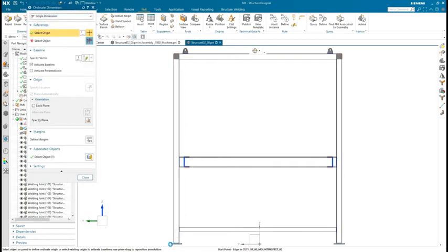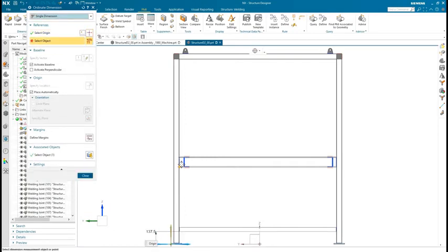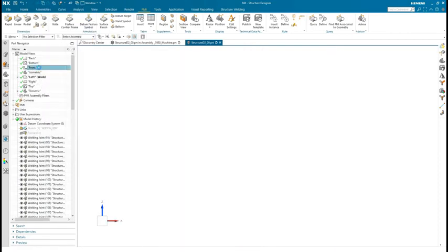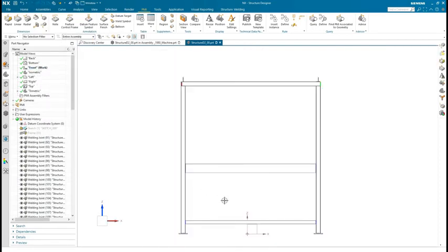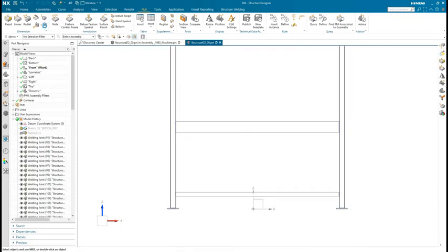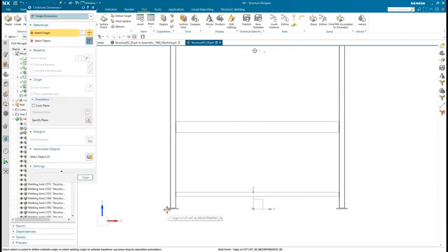We'll start with ordinate dimensions on the left view. We'll only need to add overall and location dimensions since the parts will have been cut to length. PMI in NX is smart enough to associate these dimensions with the correct view plane. Then later during viewing, recalling that view shows these dimensions. We'll repeat this process for the front and top views.